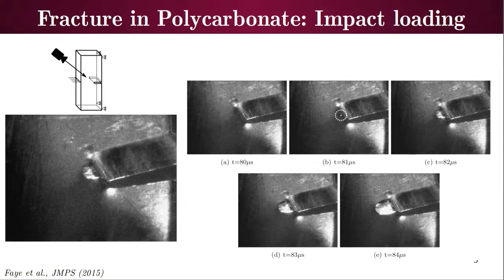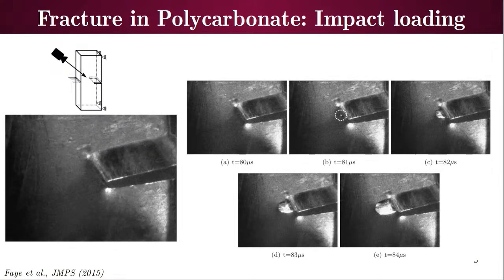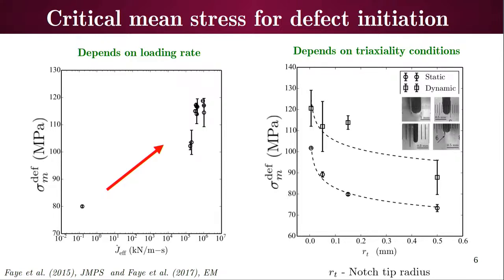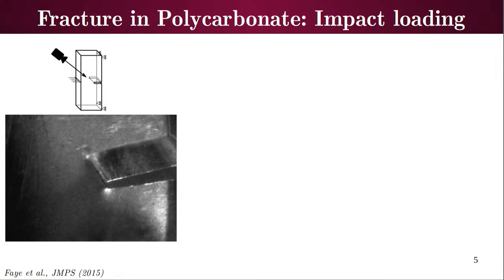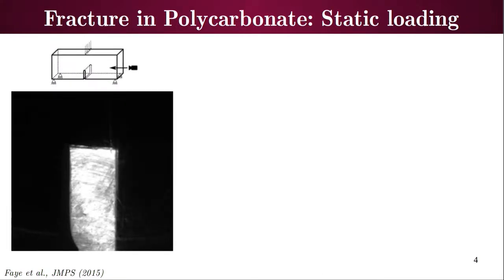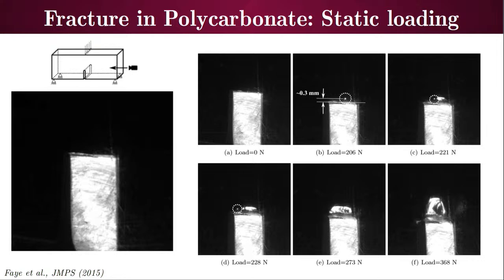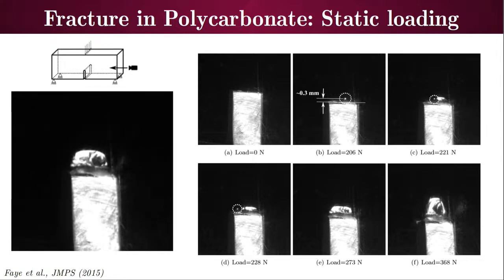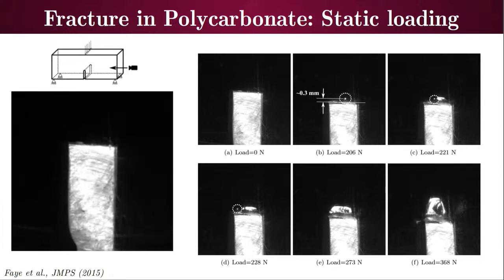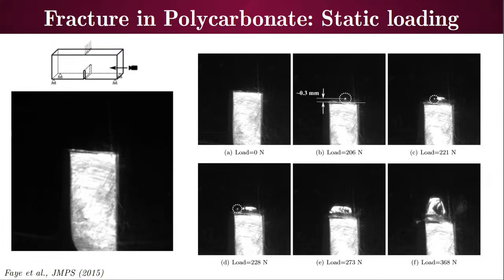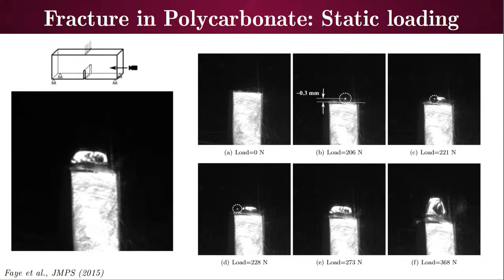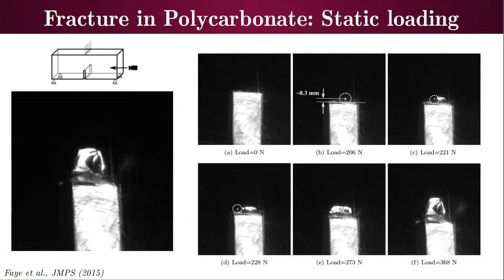So this is the phenomenon which I actually analyzed during my PhD, and what we saw with the help of simulations, that the mean stress, so basically if we consider this defect, we are seeing it in more or less a two-dimensional manner. We don't know whether this is a void or what kind of shape it has, but since a void is a good assumption for any defect in the structure, we assume that it is a void, because mean stress or pressure is generally responsible for the expansion of voids.